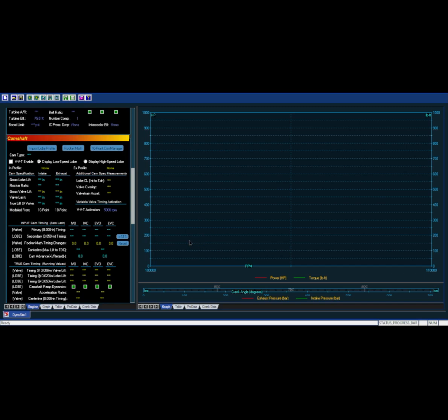So it's going to be the stock 360 truck cam. It's a pretty puny cam by today's standards, not a whole lot of lift, not a whole lot of duration. That's why these things make a lot of low end torque, and then it just fades away as you get to the top end.